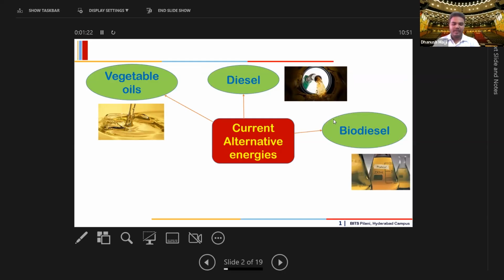Now biodiesel, which is obtained when vegetable oil is trans-esterified. This is also used as a diesel replacement nowadays. But biodiesel is vulnerable to oxidation because it has deteriorating effects on polymeric components of the engine at high temperature, which may lead to serious operational problems.